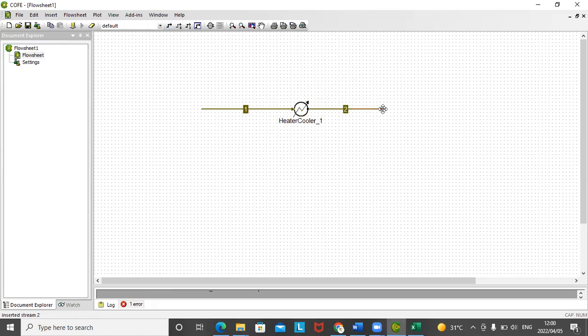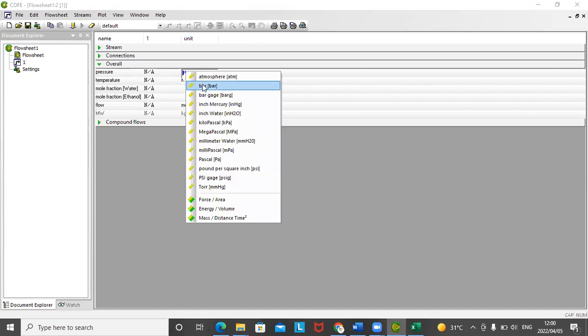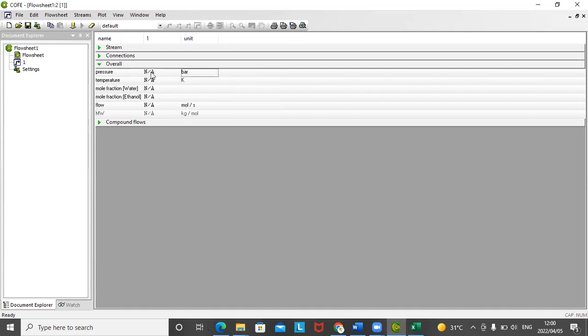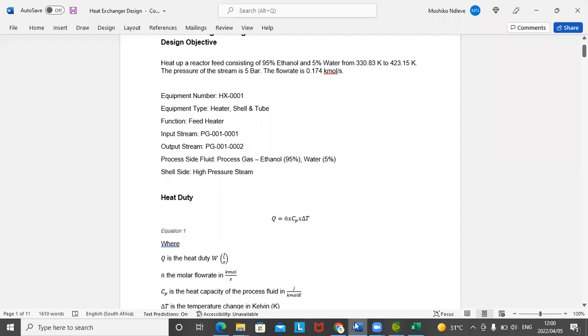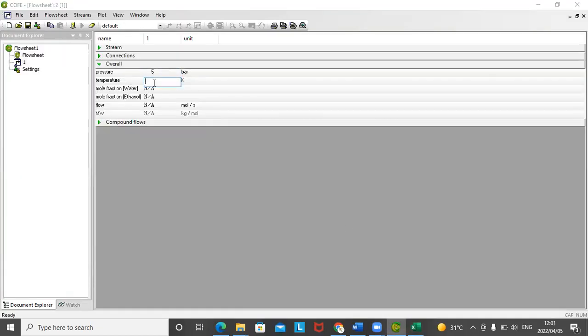Right, and what needs to come in here is, we said we're operating at 5 bar, so I'll change that to 5 bar. Our stream is coming in at 330.83. Let's go back to the simulator. At 330.83 Kelvin, right? And the mole fractions we have,